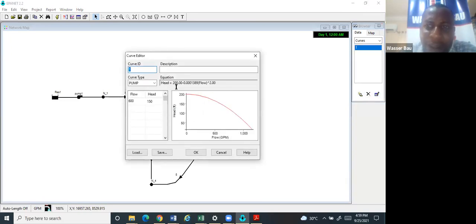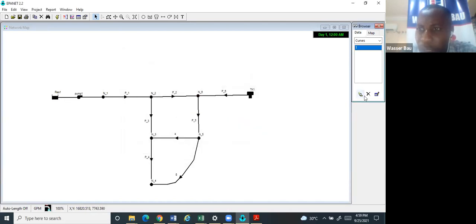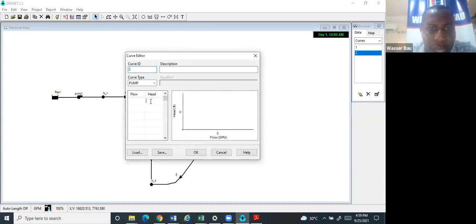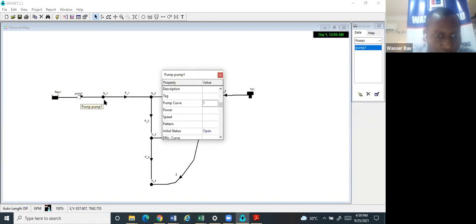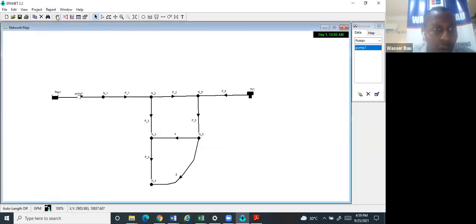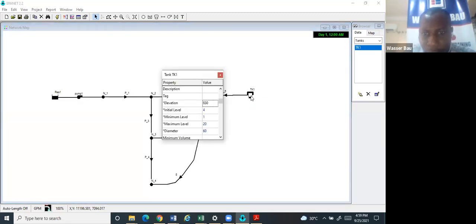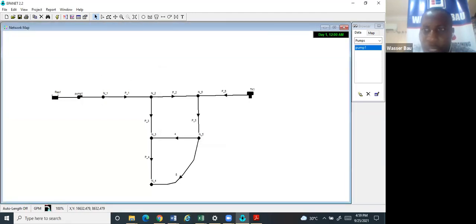So if I create a new pump now, I'll call it pump 2. Okay, let me show you now. Let me create a new pump and call it pump 2, and I'll give it a head of 100 and a flow of 600. I'll click OK, double click on this pump and say 2. Okay, let me try to run. Okay, it's giving me 100. I'm surprised it's running. Pump curve 2.